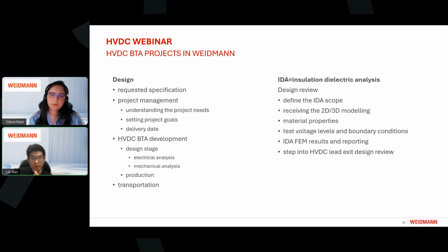But we also have the IDA, which means insulation dielectric analysis. This is a design review where we define the scope of the IDA, receive the 2D and 3D modeling, define the material properties, agree on the voltage levels and the boundary conditions, and start the calculation and reporting. So those are the steps for the bushing test arrangement calculation, design or review.